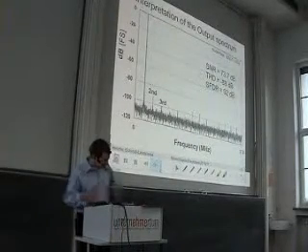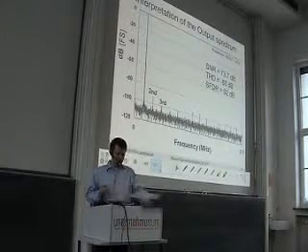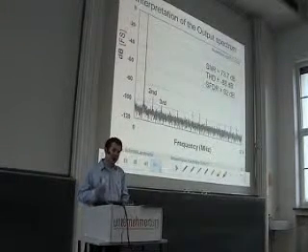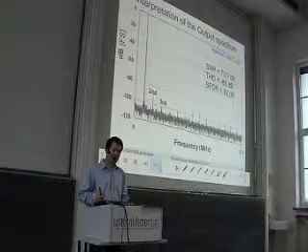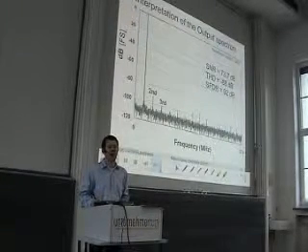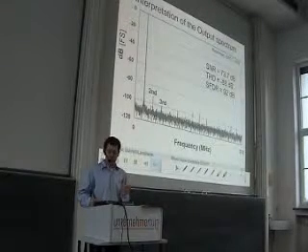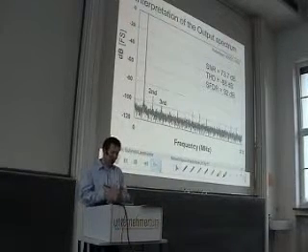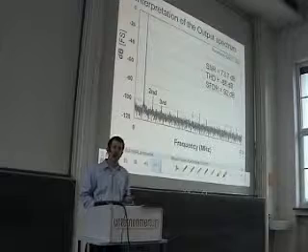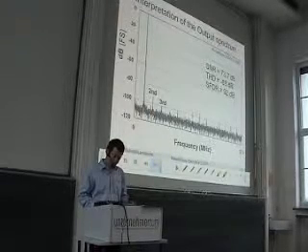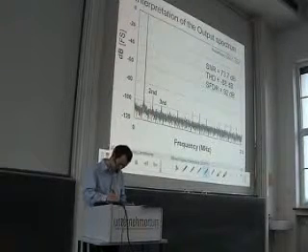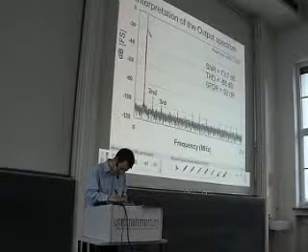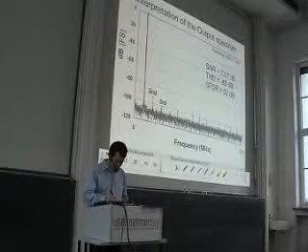So the question is, how can we understand this measurement? Well, the first thing we see is that there is indeed a significant peak. So in this illustration, which is typical for FFT, we look from 0 frequency to half of the sampling frequency. So the second Dirac you mentioned is symmetrically mirrored at a negative frequency. So it is also there. But we can see here, this corresponds to our Dirac. This is our test signal. And this is at our frequency omega.